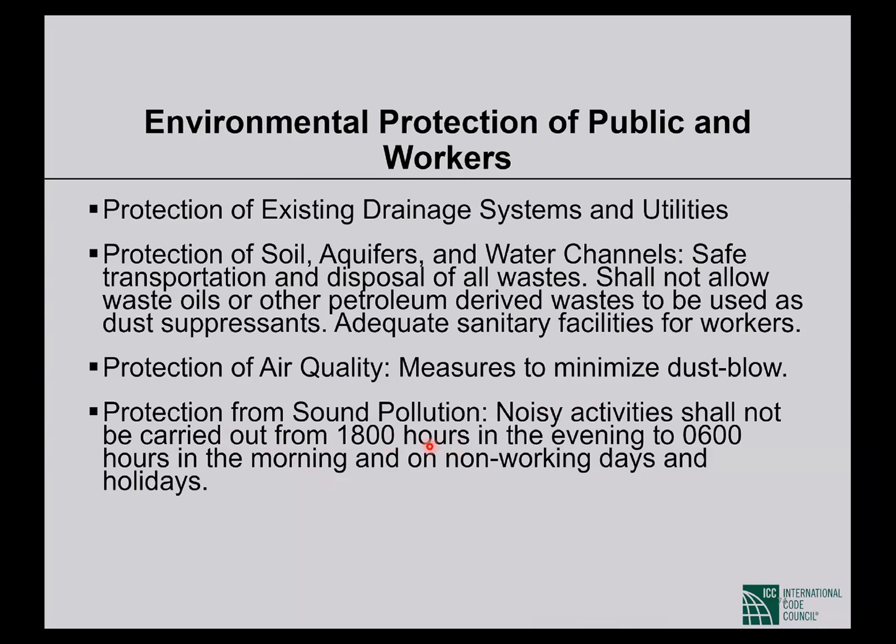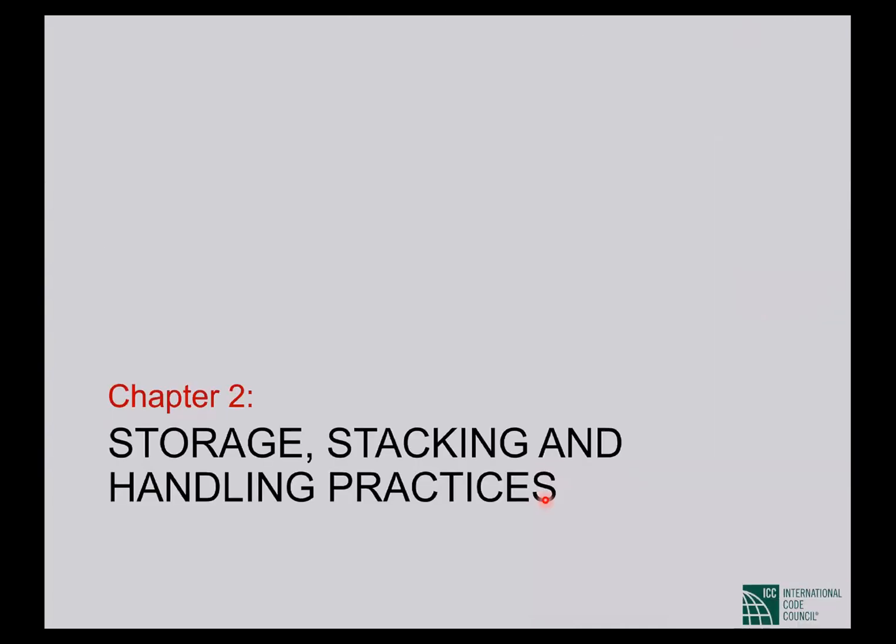You cannot continue construction activities in the evening and in the very early morning and on holidays. And there is actually a specific amount of noise, in terms of decibels, that is mentioned, up to which you can make sound.